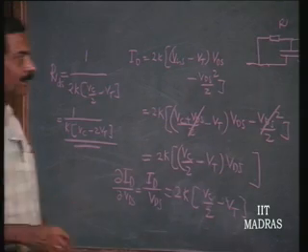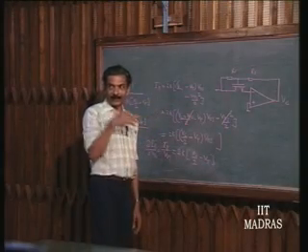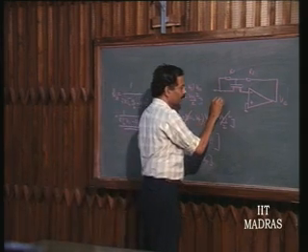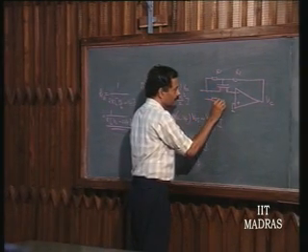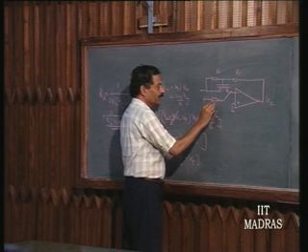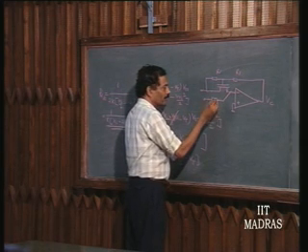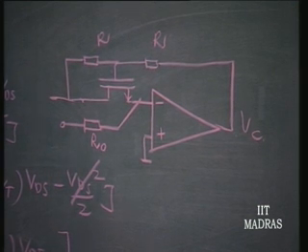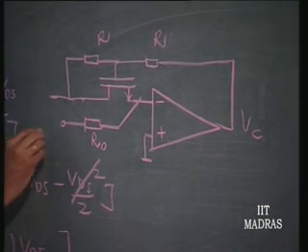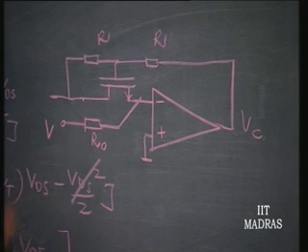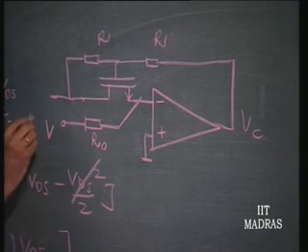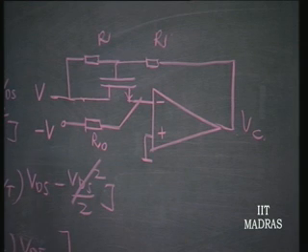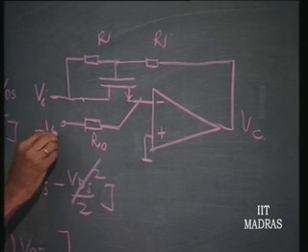So, how do I establish this resistance that I want to be simulated? That can be done by feedback. Now, what I do is put a resistance here. I make this R naught, a reference resistance. Apply a voltage V here, and minus V here. So, this is Vi, I put minus Vi here.